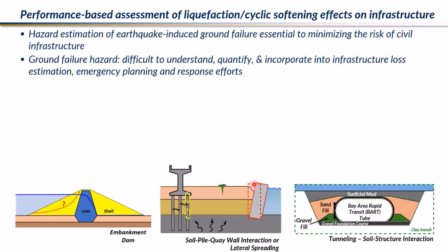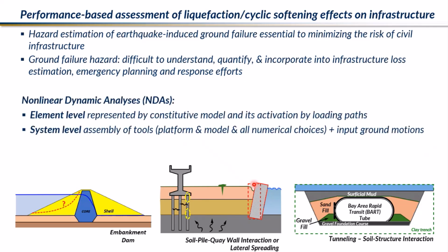As Al mentioned, my focus is to enable the performance-based assessment of liquefaction or cyclic softening effects on civil infrastructure. Admittedly, the estimation of these hazards, especially when the ground comes into play, is particularly challenging. So we're doing everything we can to understand it, quantify it, and then incorporate it into our decision-making procedures. In this, nonlinear dynamic analyses come into play, and they have proven to be great tools. At the element level, the behavior is represented by the constitutive model and how that is activated by the different loading paths that may dominate in each system.